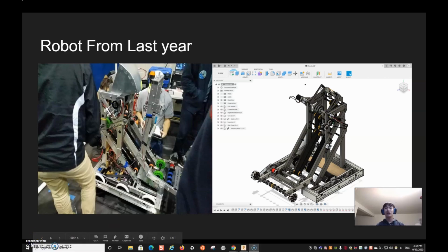So while we had Mecanum wheels on our intake last year, which would allow any ball around this vicinity to go towards the center and be pulled in by the actual spinning wheels, the Mecanum wheels were a little too small, so they didn't have that much power in pushing left or right, and it really just served the purpose of shoving balls under our robot, which caused jams and stuff. So that was an issue, and now the component I wanted to go over is the shooting hood.